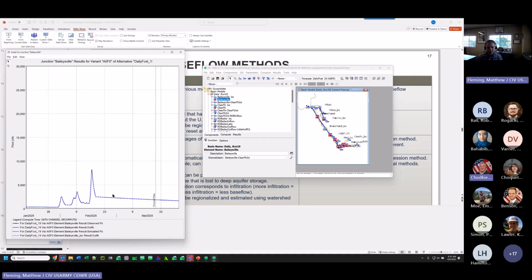And you notice with recession, once you get to a certain point on the receding limb of the hydrograph, then this recession curve just turns on, right? You have very little control over the volume. Like there is no control on volume here. And visually, when I look at this figure right here, it looks like more volume is being generated in the runoff than actual precipitation, because there is a ton of volume under this recession curve right here.